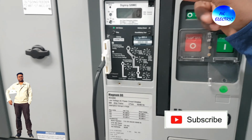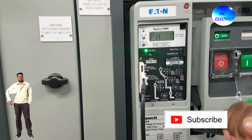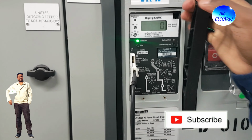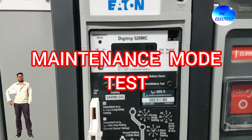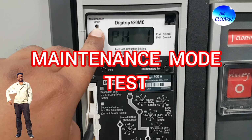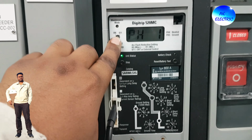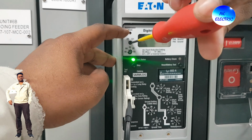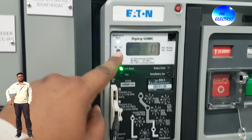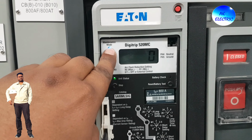Okay, now we can check the maintenance mode. See here, in this breaker we have this maintenance mode. This maintenance mode also we have to verify. For that we have to put this in on condition. Once we put it on, the blue light will come. So we have to verify this unit also.